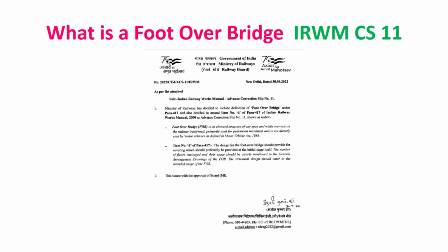This is something I am trying to share with you, because suppose the electrical department comes and says I need to have a provision of a transformer in the building complex. Then, from our information point of view, how much clear space should I keep from the wall in case they are keeping the transformer? If it has walls on two sides, then 0.75 meters should be the clearance between the wall and the transformer face. Likewise, if it is on three sides, then it is not 0.75, it is 1 meter.